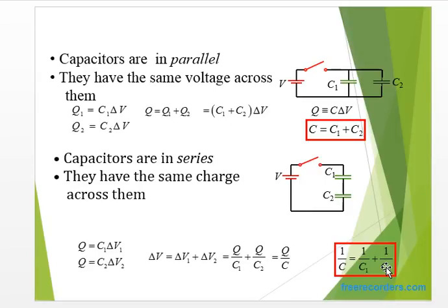If you analyze these two equations, we will say capacitors in series behave as if resistors are in parallel. Capacitors in parallel behave as if resistors are in series. So it is easy to remember the formula when capacitors are in parallel and when capacitors are in series.